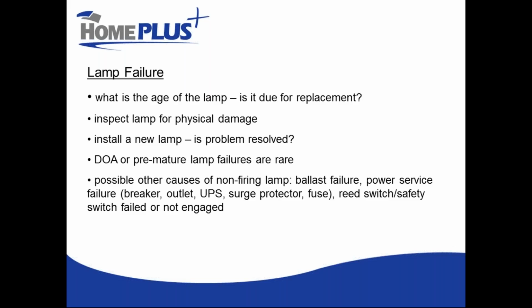And the reason for that is that it's going to impact taste and odor. Most consumers would have a negative perception of water that had more than 1 ppm in it or 1 milligram per liter. However, if you don't have a lot of contact time, in order for the chlorine to do its job, you may need to provide chlorination that is that high.